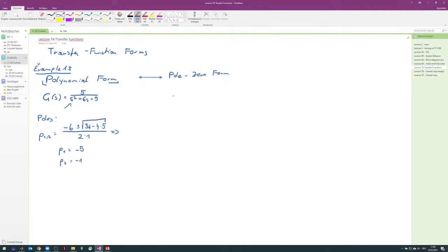So we can write the whole system now in the pole zero form. We write the poles. Take care, you need to change sign here, as plus 1. So the question is always what goes here, and therefore we need to compute the static gain. Remember, the static gain tells you, for example, if you put in a step, where your system output goes to in steady state if you just wait long enough, right? So this is what the static gain tells you.